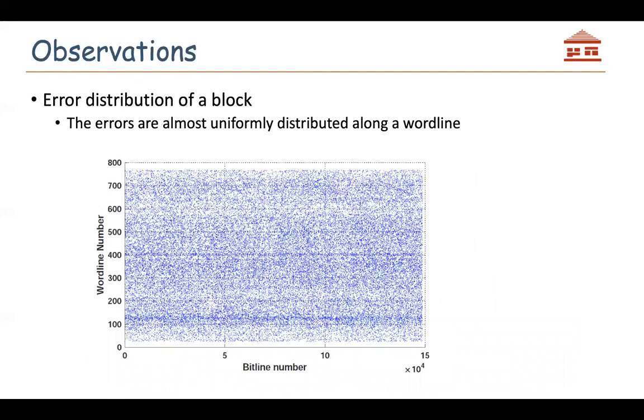We then present the positions of error cells inside one block of the evaluated flash chips. In the figure, each blue dot represents a cell that has a bit error. The dark and light horizontal stripes show that the RBR varies greatly among different word lines. Therefore, the error characteristic of one word line cannot represent the error characteristics of other word lines inside the same block.